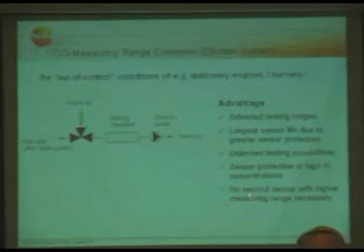And then, because of this dilution system, no second sensor with higher measuring range is necessary. This is our philosophy: to provide such a dilution system, and then you can use your specific sensor and extend the measuring range according to your dilution factor.